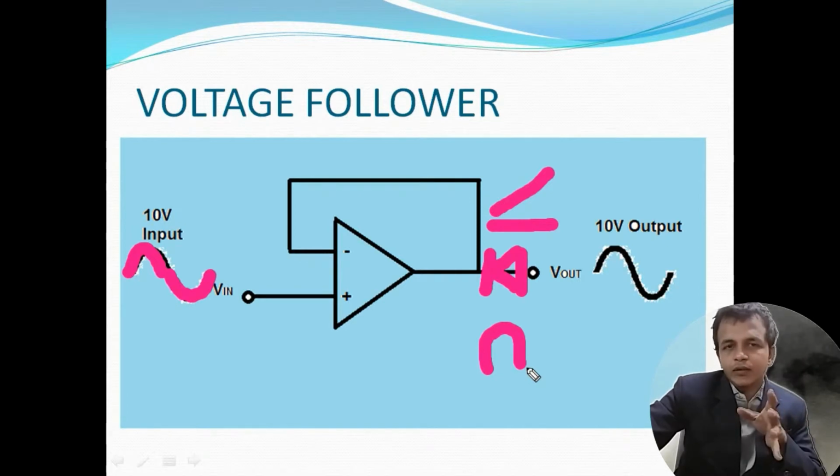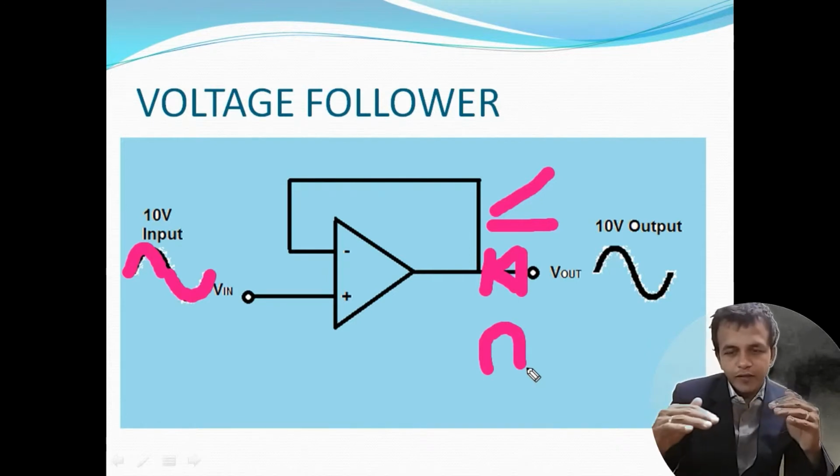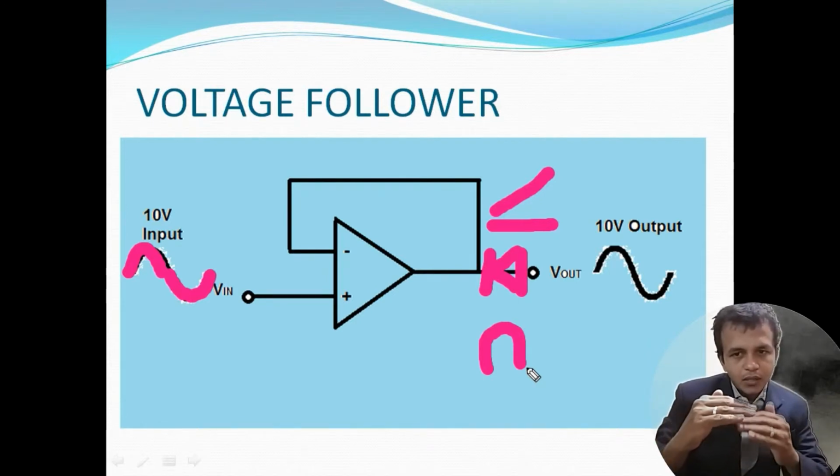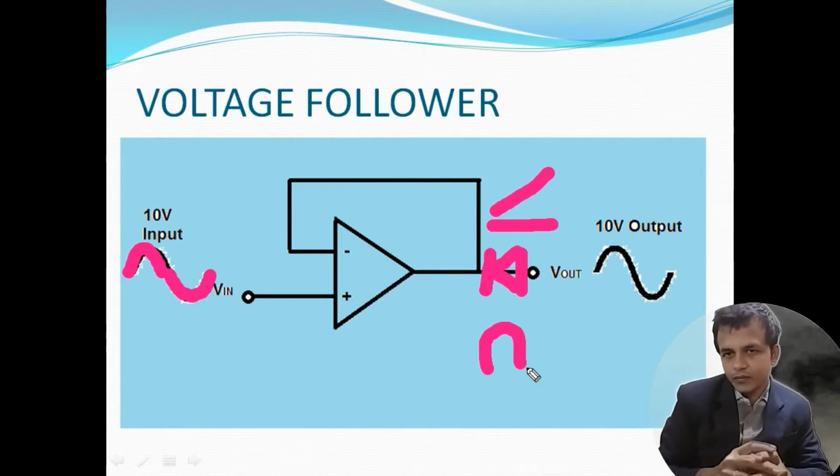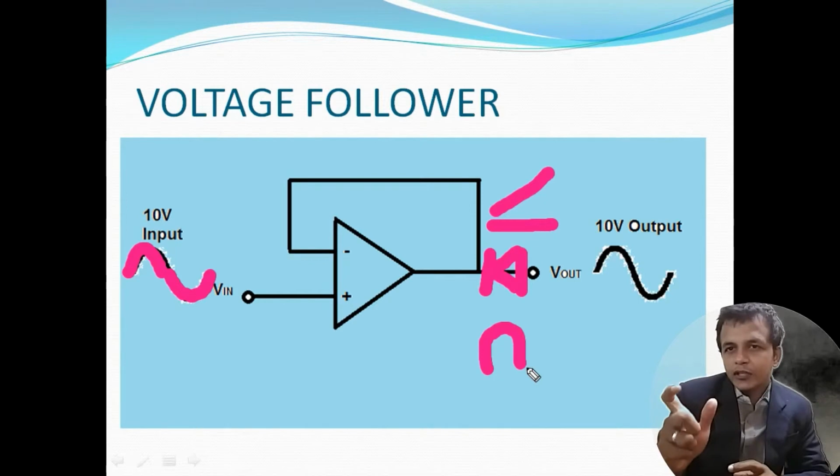But for our requirement, we are producing a clipping circuit, a clipper circuit. For that, some portion of the negative region or some portion of the positive region should be eliminated, not entirely, and it should not be biased to the single direction. So where should we connect this diode to do that operation? That is an important thing.